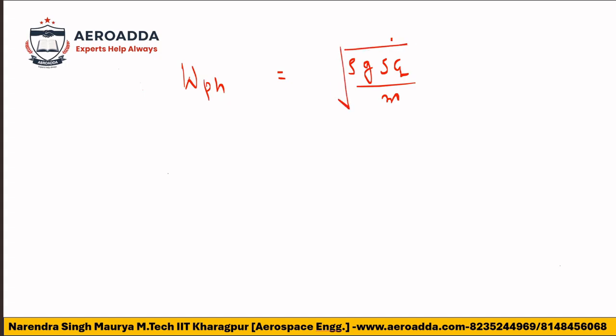Now, if you want to convert into velocities, what you will do? I had shown you for the steady level lift, L naught was there, and L naught was, because it's steady level, equal to mg. This is equal to mg, right? So see, and also you know the lift formula. So what is the formula? 1/2 rho v naught square S into CL.